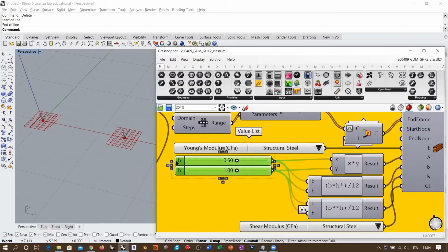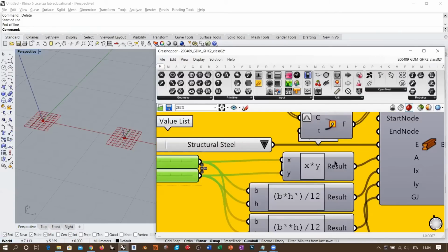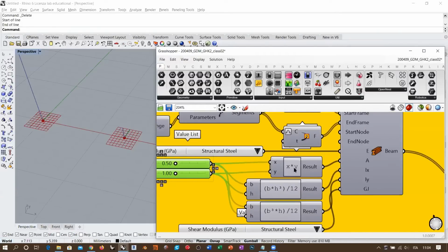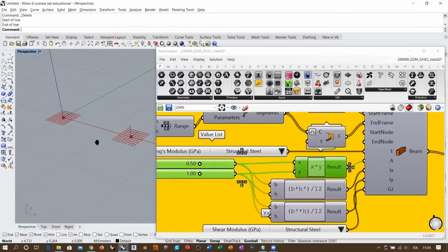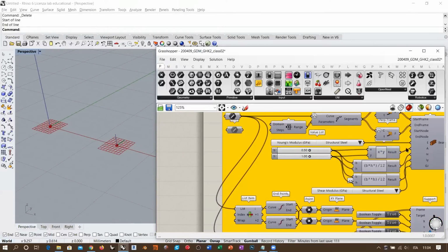So here we are taking base and height. We are multiplying the base by height, considering this is a rectangular cross section. But if you don't have a rectangular cross section, you must work with this thing here in order to simulate, for example, a round cross section. Then you might define the round cross section by radius, and you will have a different expression, which would be radius squared by pi, okay? So everything is related to the shape you want to simulate.